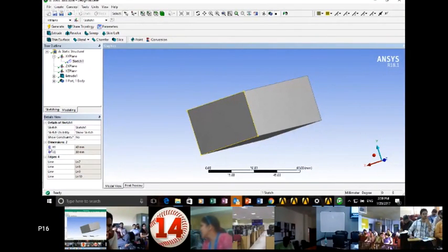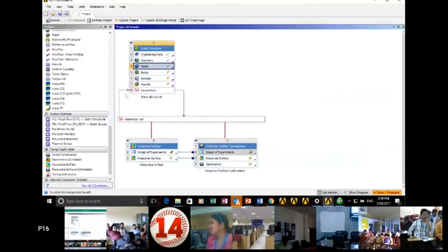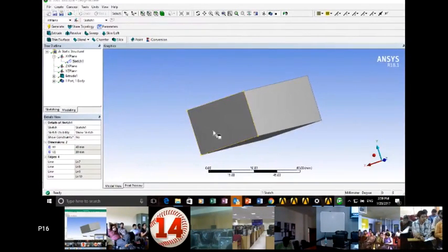You can see over here I have put a parameterization for height and width. Now whenever you put parameterization by checking the checkbox next to certain values or parameters, then in ANSYS Workbench it creates an independent parameter set which will be used as a relation, in the form of an equation, to manipulate your results based on the values which we have given as input. So here I have parameterized the cross-sectional size.